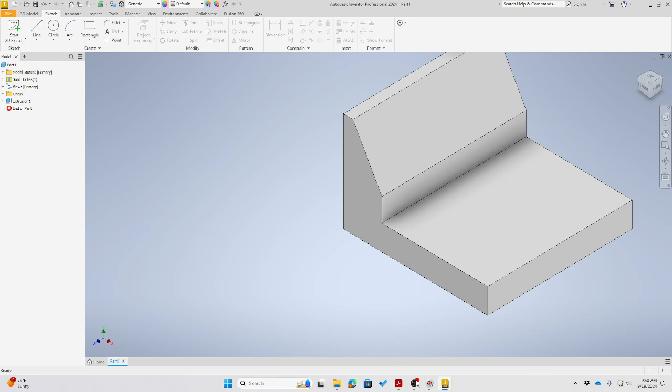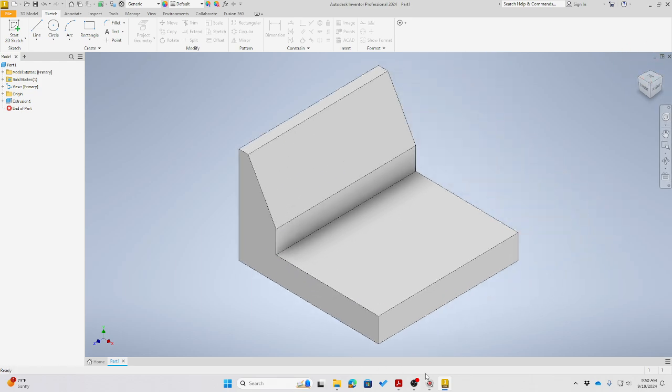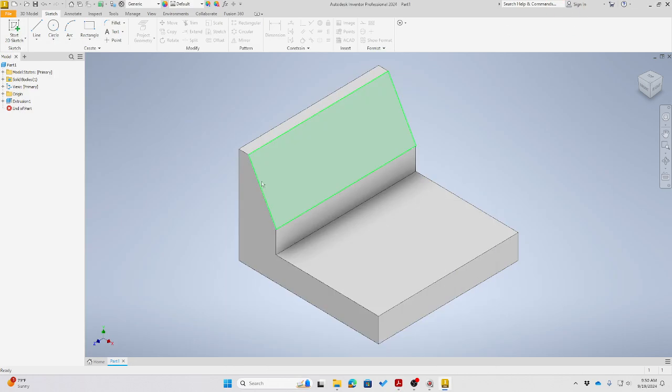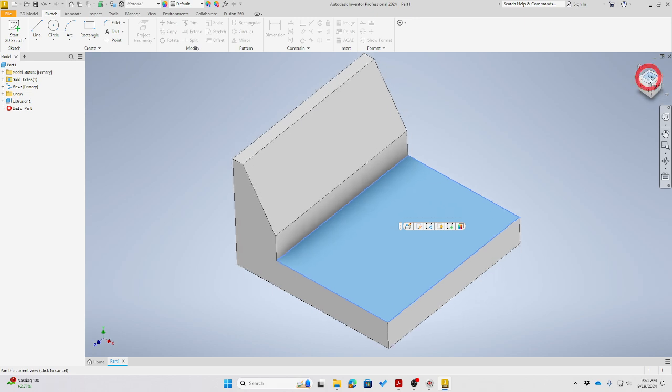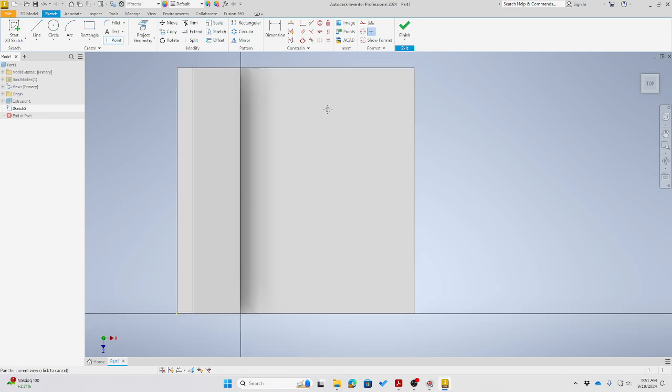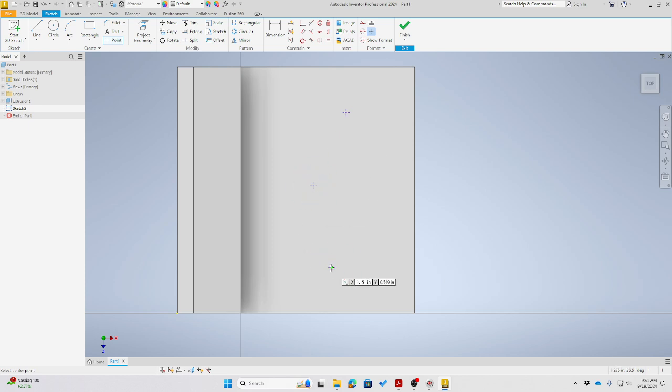We want now to consider drawing this circle, this hole, using the hole feature in Inventor. To do that, we need to use the points here, and to create a point we need to select the surface. So select this surface, top view, and now click the point, and just select 3 points on the surface. I'm selecting randomly. First constraint and most important constraint, these 3 points should be aligned together.